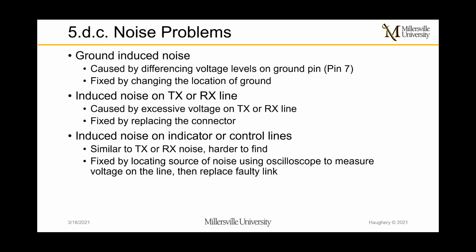You may also get induced noise on the control lines themselves. It's kind of the same as the issue with the TX or RX lines, but it's a lot more difficult to find where the issue is. So you can try using an oscilloscope to measure the voltage on the line to find which line is faulty, and then you can try replacing that link.